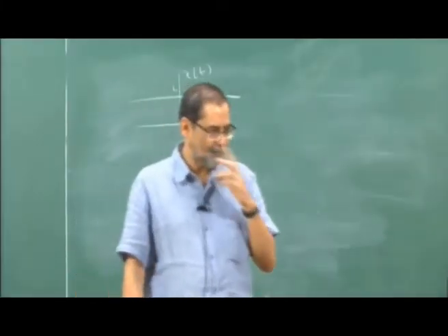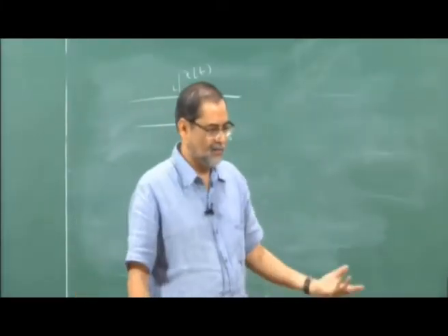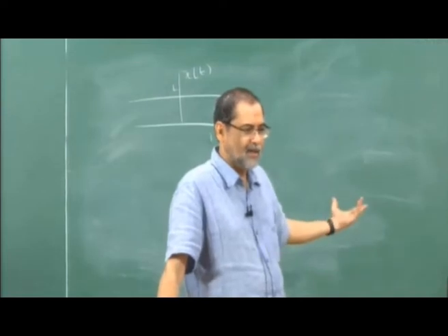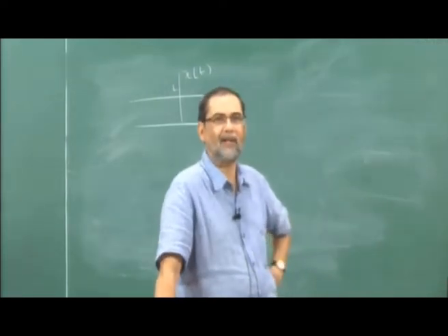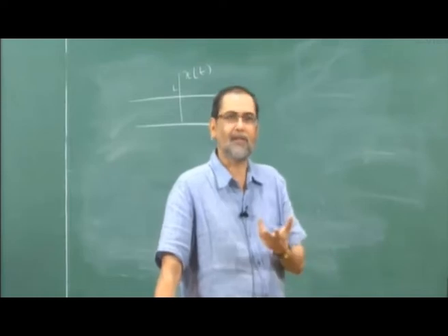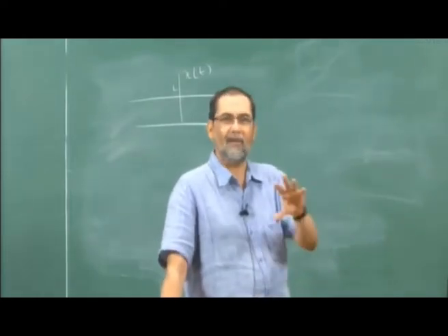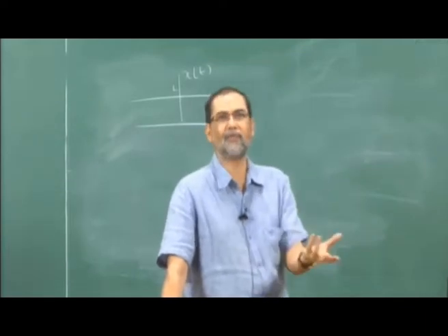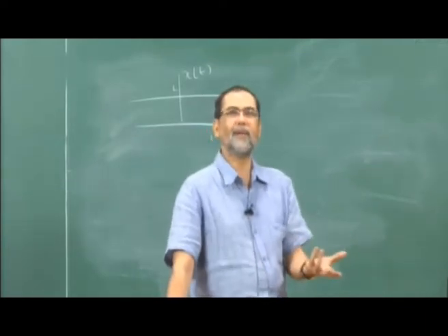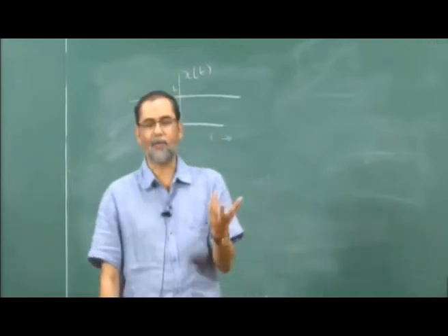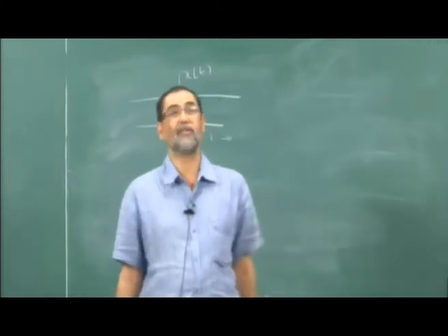So by itself, this cannot be convolved straight away. If t goes from minus to plus infinity, when you flip it and shift it, that still goes from minus to plus infinity. So it appears that the integral is improper and doesn't converge, so convolution is not defined.